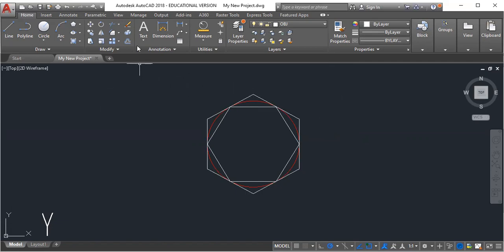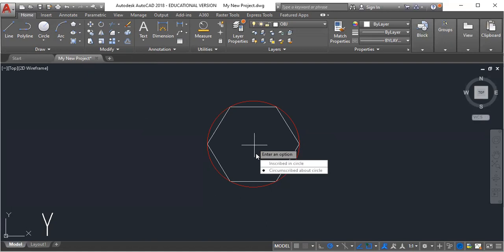We can do the same thing. I'm going to undo that, and we can draw a polygon and put it in the same center. Oh, number of sides. Let's make this 17-sided polygon. Something really weird. Enter. AutoCAD doesn't have any problem with that. Just wants to know where the center is. We're going to put it on the center of that circle, and we're going to circumscribe it.